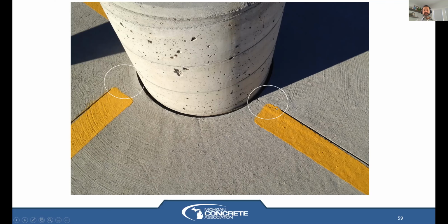The fact that the crack actually occurred at the joint is great. And the fact that it is in line with our joint, and our joints are in line with our structures, this looks perfect to me. I don't see an option with this. If this is a concern, because obviously the light pole bases were placed first and the vertical obstruction was there, you could go in with some joint sealant material and fill up that crack if you're worried about it spalling.